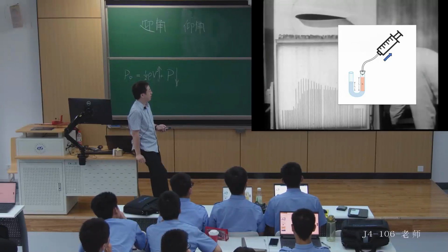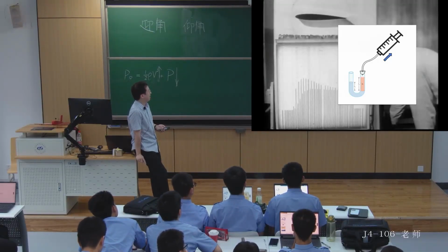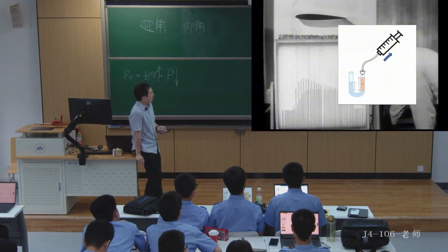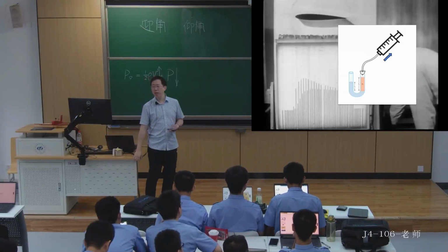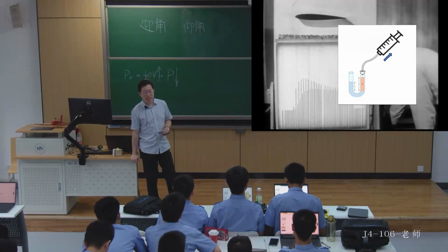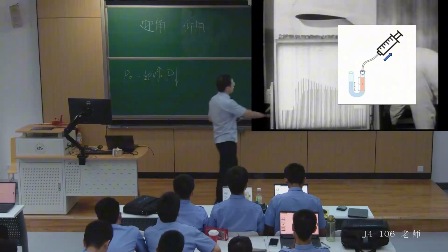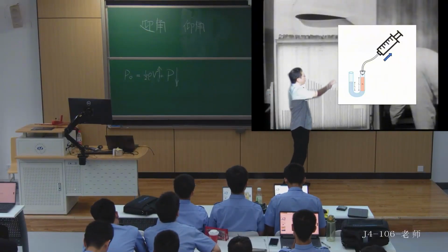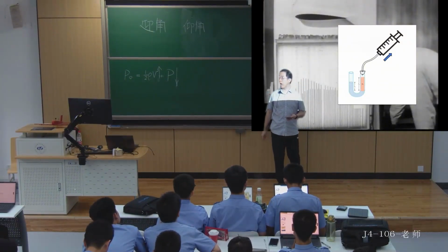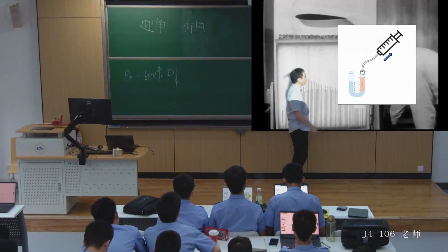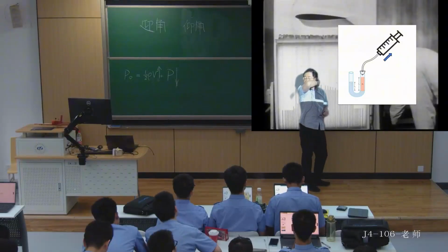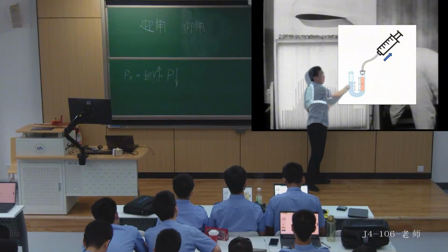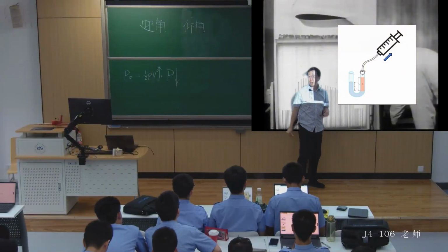These tubes are connected to the model alternately from the top and bottom. So here, this is essentially a type of side pressure wind tunnel. How does it fundamentally work? As we can observe, these tubes below are all U-shaped tubes, and one end of each U-tube is connected directly to the surface of the airfoil. The other end is directly open to the atmosphere.